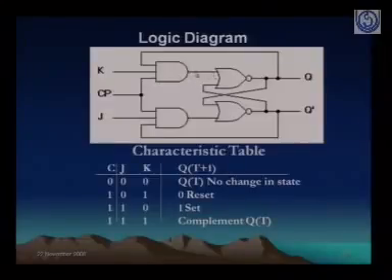So what is the input on this particular side? It is 1, right? So this basically represents your R, the reset value, which is 1, whereas J is 1 and Q dash is 0, so the set input is 0. So you get the reset value as 1 and the set value as 0.